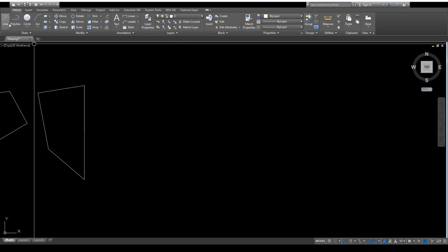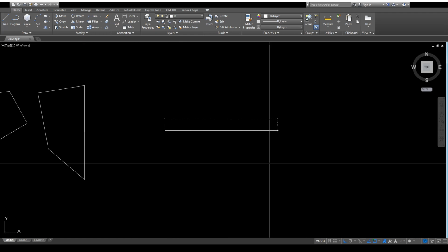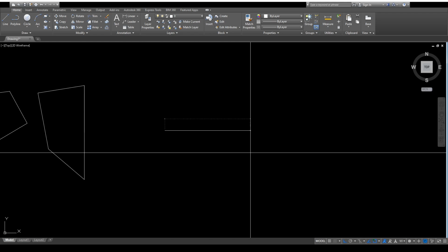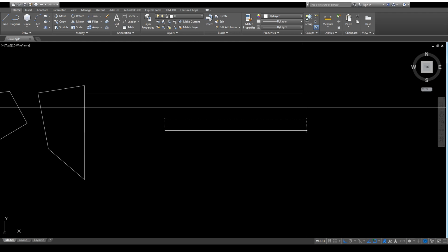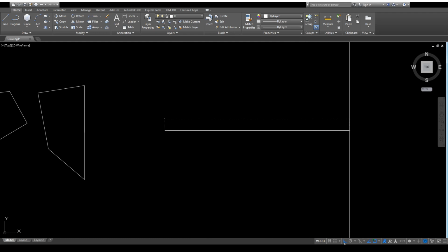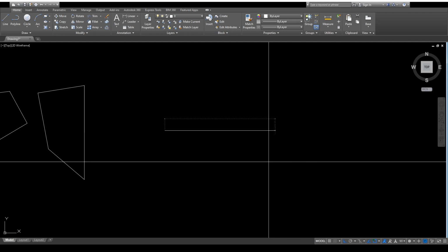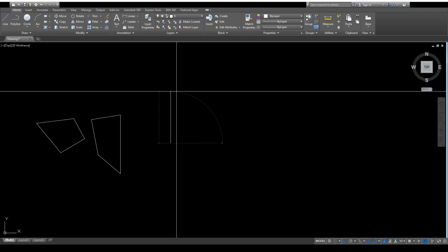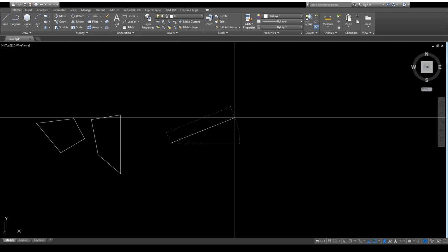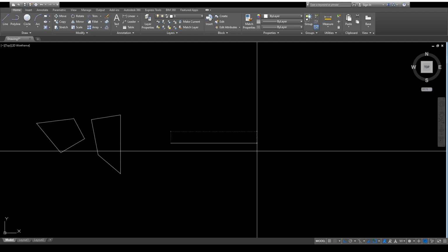So, if I click yung line, click akong isa, ayan. Pag drinag ko siya, hindi katulad kanina na naka-incline yung line or kung saan ko drinag yung mouse, nandun siya. Nagiging automatic na horizontal line siya kung naka-activate yung ortho mode. Ang toggle for that is F8. So, since naka-on siya, naka-blue siya, horizontal and vertical yung automatic na pwede kong i-drawing. If I press F8, ayun, automatic nawawala yung drawing capability niya for horizontal at saka vertical. So, press ko ulit yung F8.